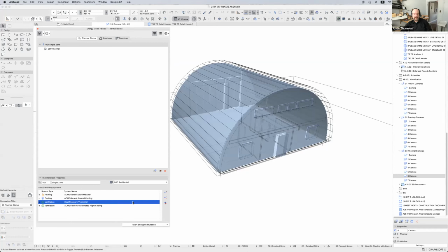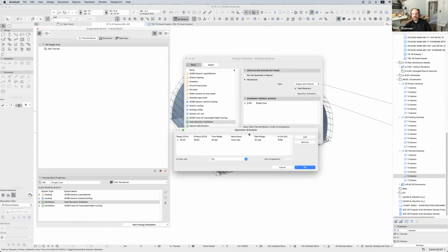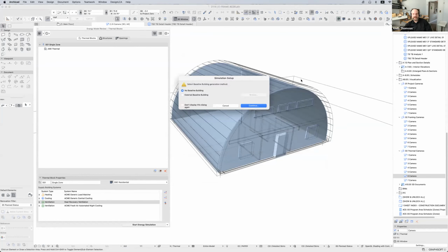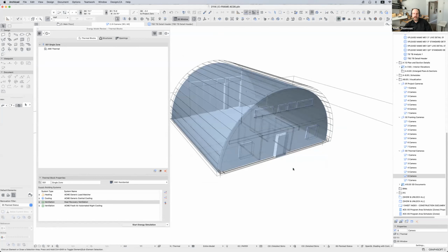And we can specify, based on F326 ventilation modeling, what is our operation schedule for our energy recovery ventilator or our heat recovery ventilator for 2 occupants in a space with 2 bedrooms. A 90 CFM unit might be doing it fine. It runs all year 24/7. So those systems then apply, and we can run the analysis again and see, are we improving our EUI?